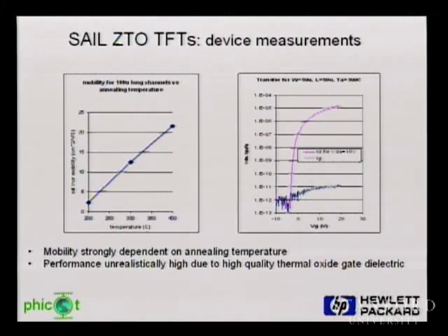We're also using the same technology to make OLEDs, and in the case of an OLED, you really need to source a lot more current. And again, that's taxing on amorphous silicon, but it's probably a lot easier to do with the zinc oxide materials.